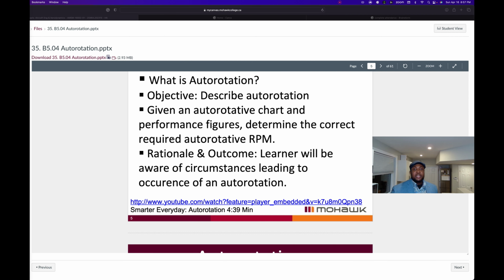The advantage here is that you are more likely to be able to generate lift and regain some of your rotor RPM if you lose it. The disadvantage is that it's very difficult to maintain proper RPM during auto rotation with the low inertia rotor system. In auto rotation, a low inertia rotor system will have less stored energy for deceleration and landing.